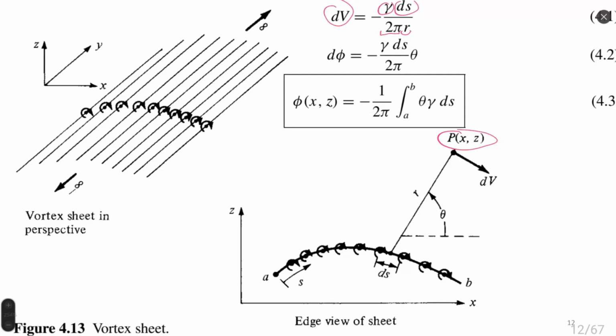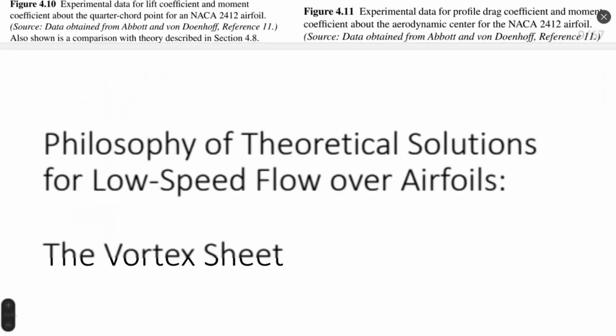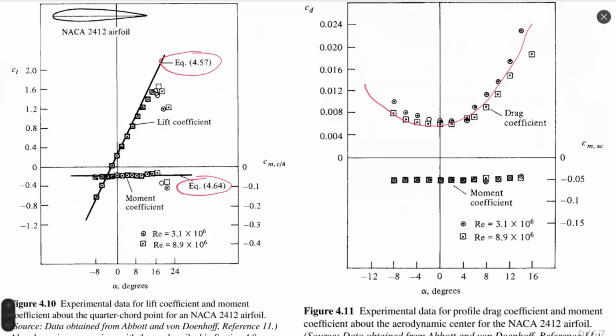It is right to approximate the drag coefficient with polynomial functions using numerical methods such as the least squares method, for example. As I told you, of course you can process experimental data. This experimental data can come from a wind tunnel or from numerical simulation. You can process these functions, but functions such as parabolic ones will not be a purely analytical solution.